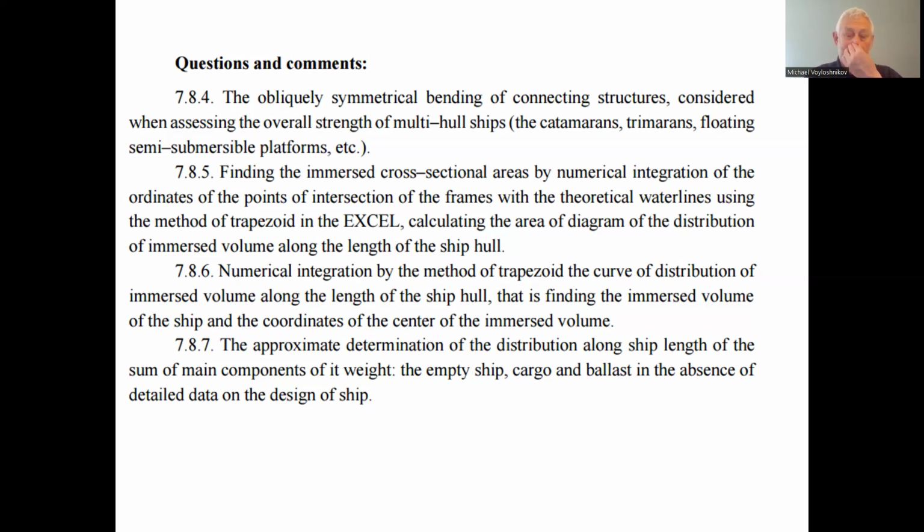And using this table, for each theoretical frame, we can find the total of the ordinates, with the adjustment of the extreme two ordinates divided by 2, and multiplying that by the distance between each two water lines, between each two ordinates within the transverse section of the ship.